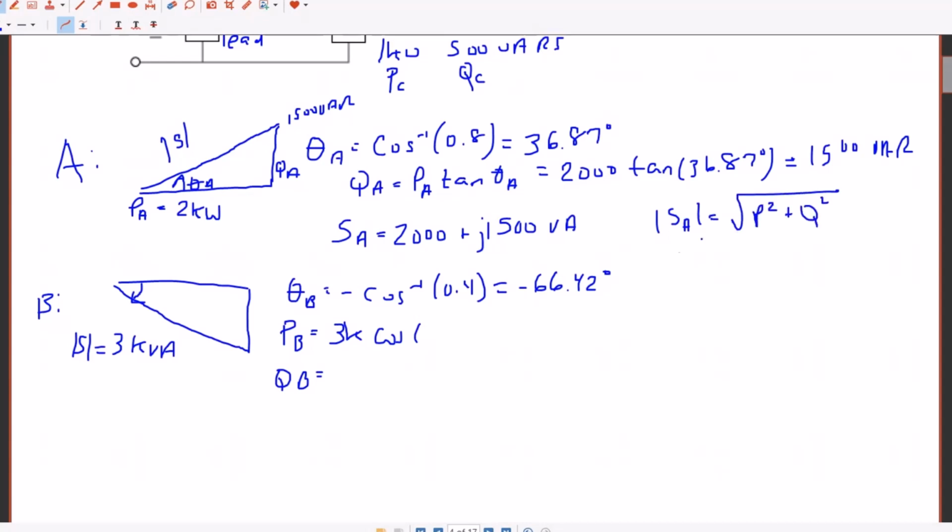One of them is the apparent power. This is the complex power. The complex power is a complex number. The apparent power is a real number, and it's the square root of P squared plus Q squared. So the magnitude of SA is the apparent power. We didn't find that number, so we don't know what that is. Does that make sense? Yes, it does. Thank you.